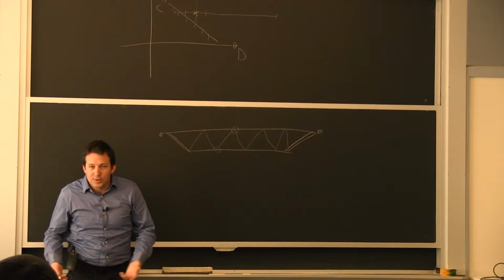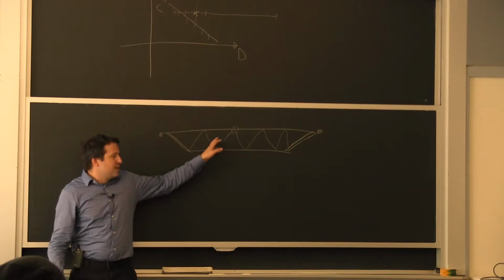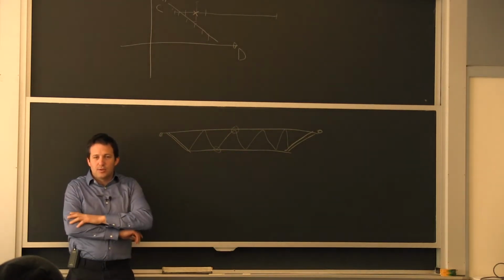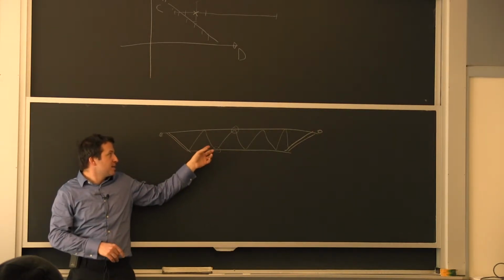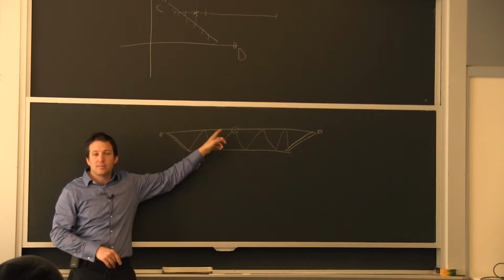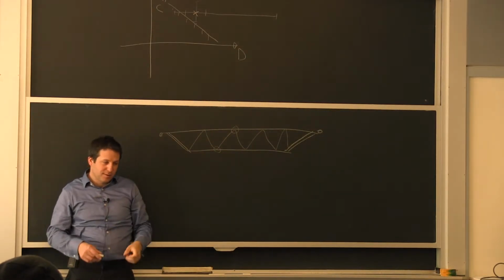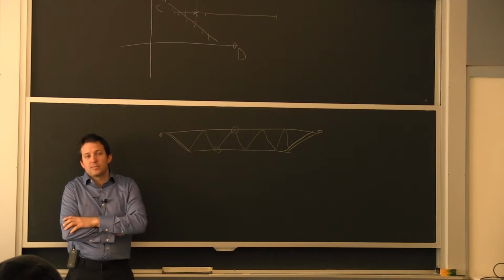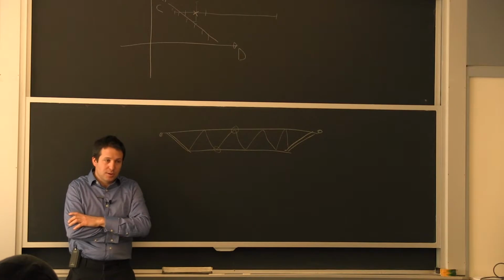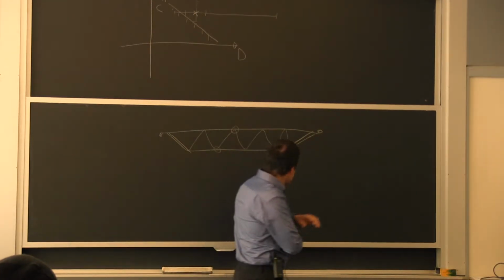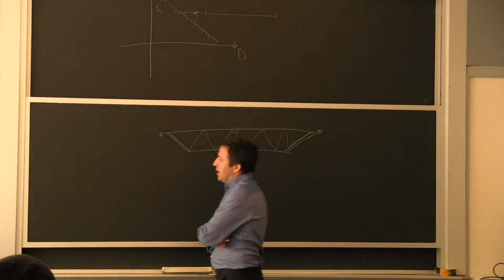There's no doubt that they'll reach the capacity you need, and it allows you to deal with some imperfection here in the core. The idea of these round bars is just so quick to make. They bend it back and forth just like I showed, and put it in, weld it, and it's over, as opposed to having multiple pieces. It's very, very efficient. Yet, if you don't control the conditions, then you have a risk of a failure.